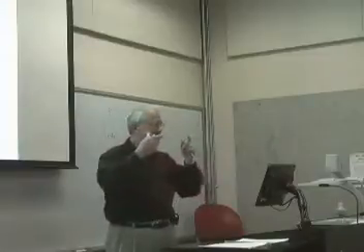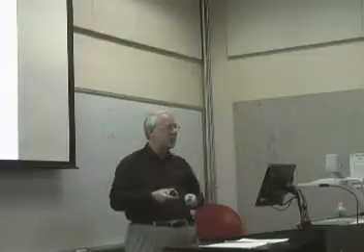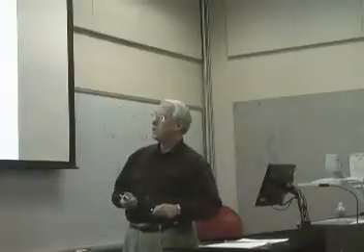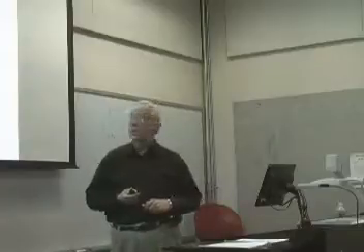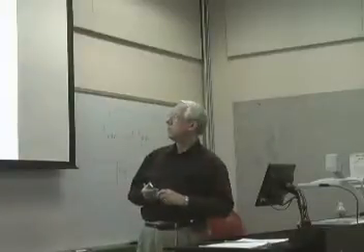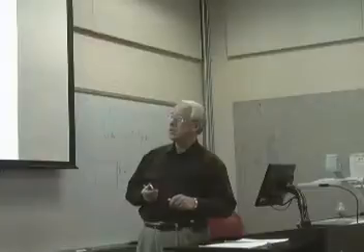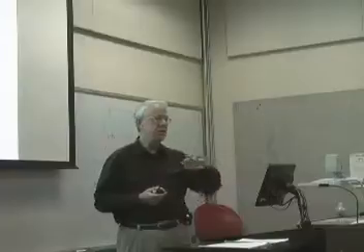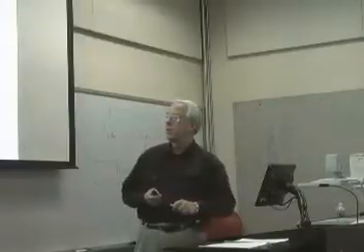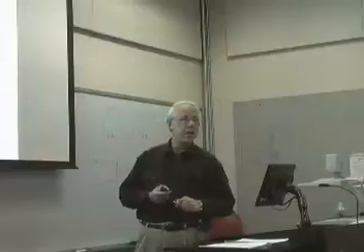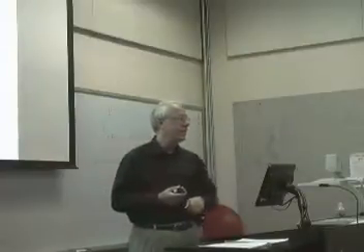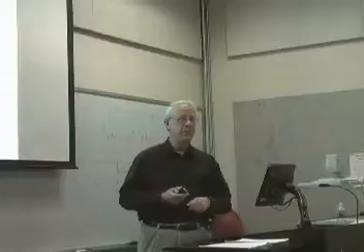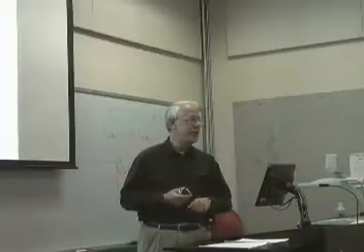If I go to 3D elements, now that I've got this thing set up and I see what's happening with regard to establishing the equation, it's easy to add just one more dimension. So here's what the 3D equation would look like for temperature, for example. So here's the diffusion terms, source or sink term. This is if there's what we call advection. Maybe there's a wind, or maybe there's a fluid that's moving the temperature around. That's what this is. So this is a mixed equation. What kind of equation is this? You got one of three choices: parabolic, elliptic, or hyperbolic.